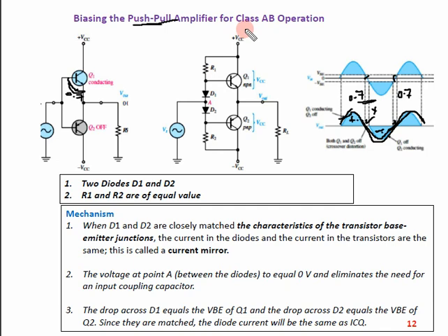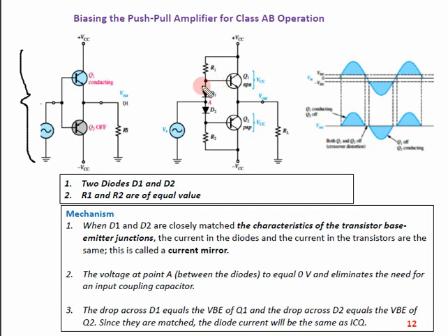So what we do is modify this circuit, the push-pull amplifier circuit, and insert a small DC biasing at the base, so that the amplifier also conducts for that region, and that is 0.7 volts. We say that we modify the push-pull amplifier to a class AB amplifier, which is in this circuit, by introducing base biasing. We can see biasing at the base over here and over here, just to make sure that both of the amplifiers conduct and there is no crossover distortion.